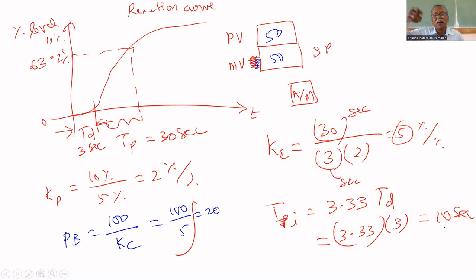Escape, if you press enter, it will display TI. Enter TI, 10 seconds. You can use the increase and decrease keys to vary the value. Enter 10 and press enter, and 10 will be accepted. Then you press escape, it will come out. So your third condition is satisfied. You entered the correct tuning parameters.